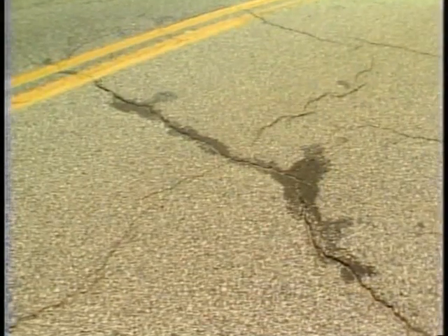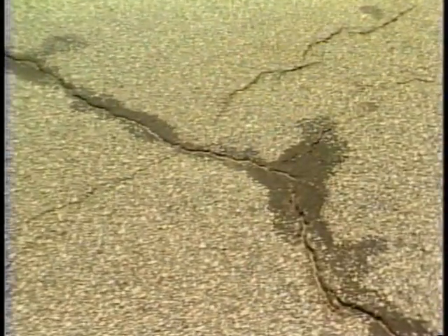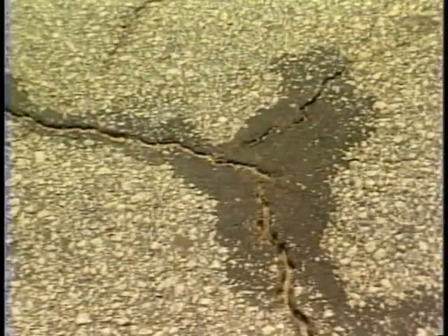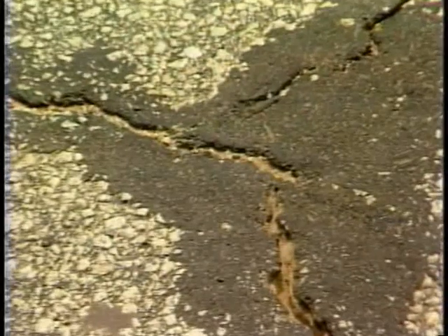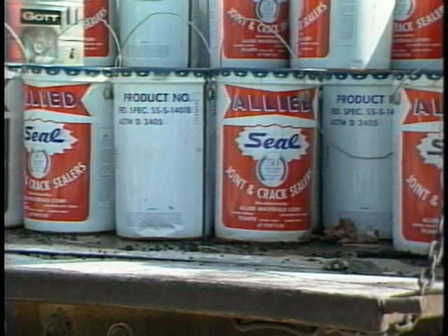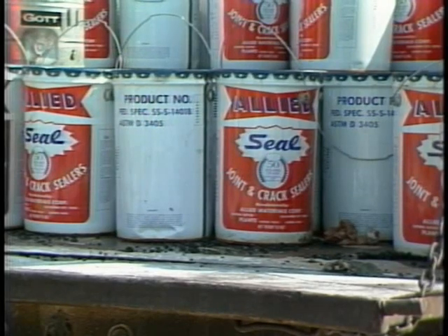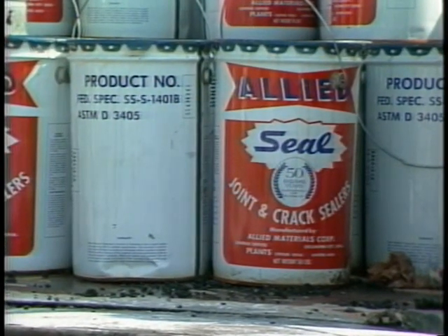In many areas, cutback asphalt, emulsified asphalt, and lean sand asphalt have been used for crack sealing. These materials have yielded mixed results, but generally provided a short service life. In response to a need for a better asphalt crack sealant, numerous proprietary sealing materials have been developed.